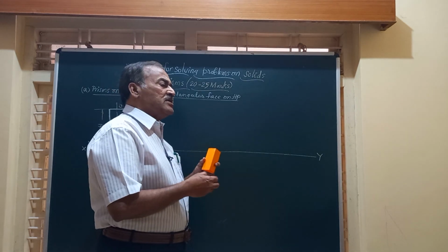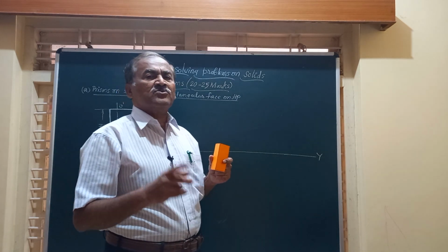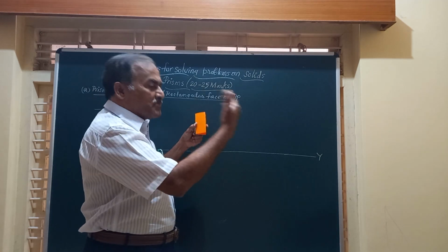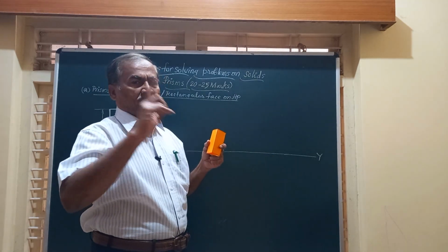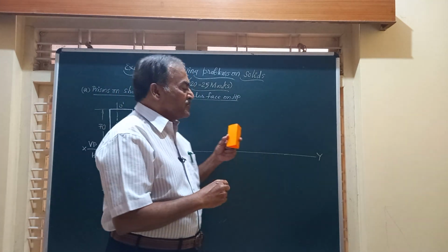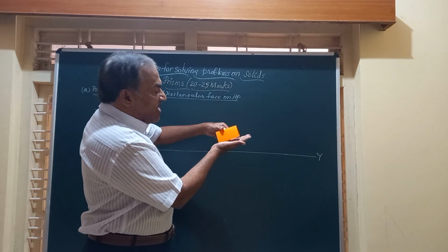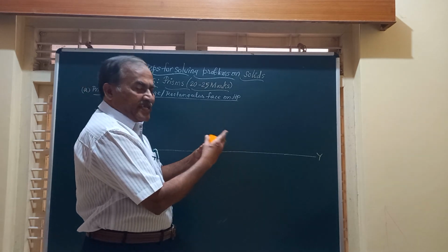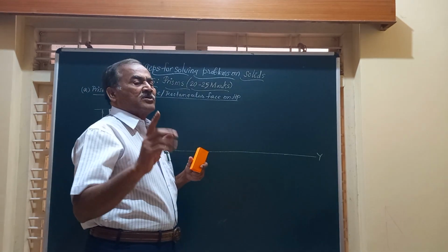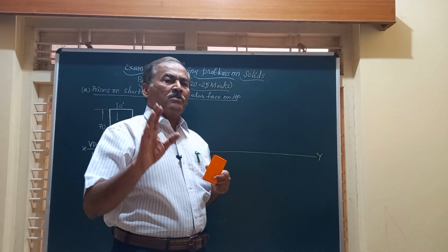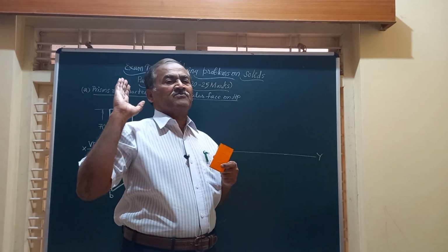So, whenever the prism has to rest on shorter edge, that shorter edge should come to your right side. Clue number one. Clue number two, whenever it has to rest on rectangular surface on HP, then again that shorter edge should come to your right. This is applicable for all problems on all types of prism.